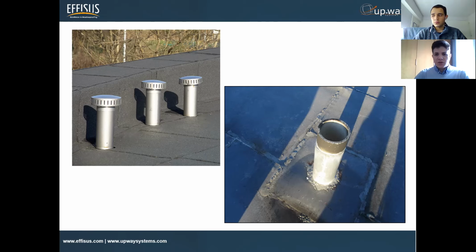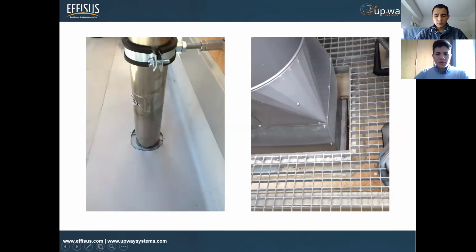For instance, you see here in this case they were sort of welded behind these penetrations. Those solutions are all right for quite a period of time, but after long exposure to UV, water and rain, they will eventually start to fail. So today we'll be discussing how these interventions should be done, and how to properly seal this type of crossing penetration, preventing pipe and duct leaks. That is today's topic.